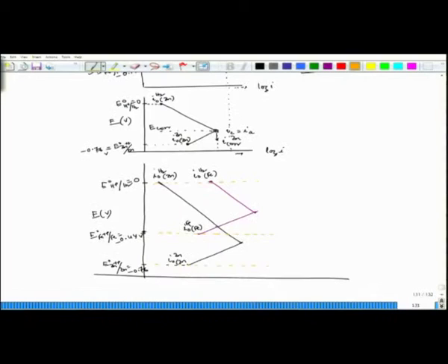Now, this is the hydrogen evolution reaction, the cathodic polarization for hydrogen reaction on zinc surface, and this is the second hydrogen evolution reaction on iron surface. So, these are two cathodic polarization lines, and then at each potential we have to add up those two current densities corresponding to these two polarization plots, and then we have to get a new polarization line. So, this is, let us say, this color I am putting blue green color.